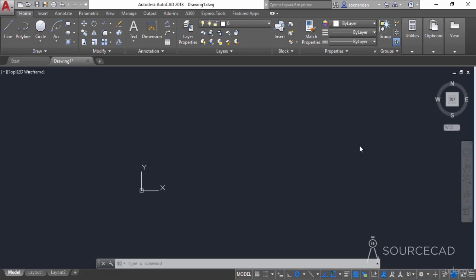In this video, I'll tell you about making rectangles in AutoCAD. So we've already seen the simple methods of making a rectangle using the line tool, but we have a direct method of making rectangles in AutoCAD as well, and that's using the rectangle tool. Here we have this rectangle tool on the draw panel, and when you expand the flyout, you'll see the rectangle tool here.